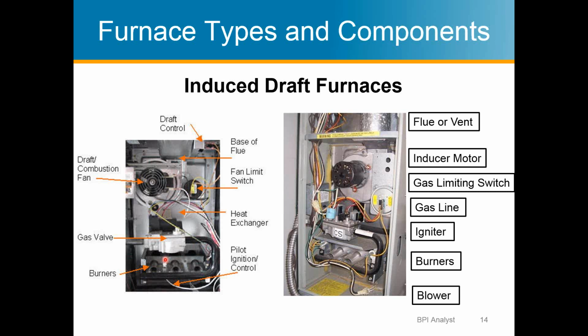That's induced draft furnaces. Like I said, if you're builders and building something today, this is typically what you see put in. It's the cheapest option and the lowest efficiency allowed. Natural draft furnaces aren't allowed to be installed any longer, at least in California.